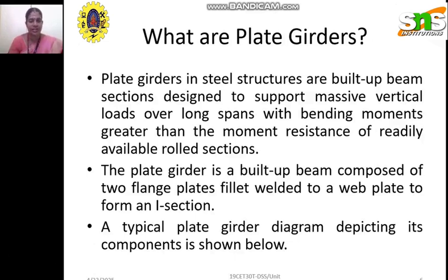So what are plate girders? This is a built up beam. For a normal beam, there may be just one section; mostly for beams we provide the I section. If you provide more than one section, that is, if you provide stiffeners and so on, it becomes a built up beam. It is mainly designed to support massive vertical loads over a long span.